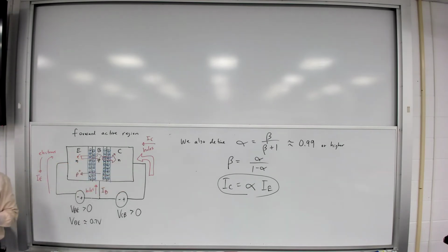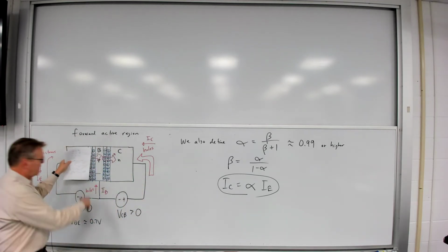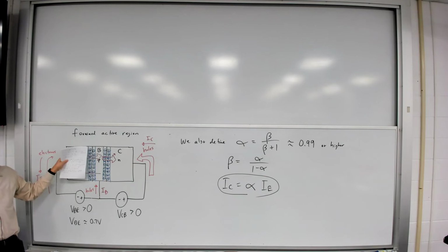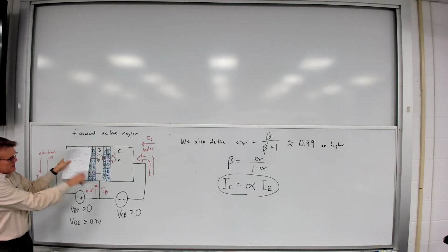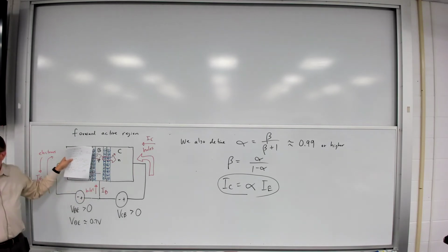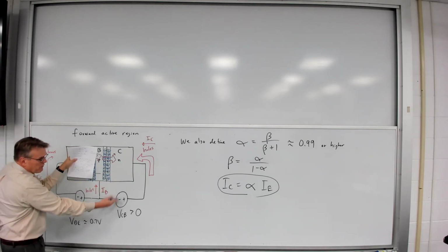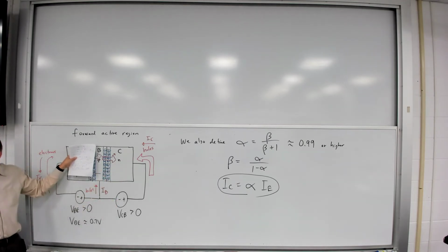Then they're swept into here, and then they're annihilated by the holes flowing through here. So if you take a reverse bias p-n junction, and once again, ignoring this, the only current that flows across a reverse bias junction is going to be the minority carriers. So normally, just by itself, if this were reverse bias, there'd be almost no current flowing across that junction.